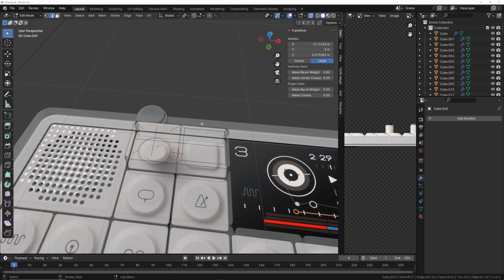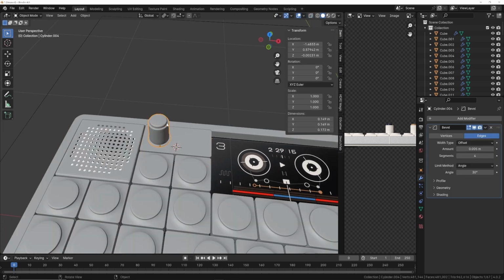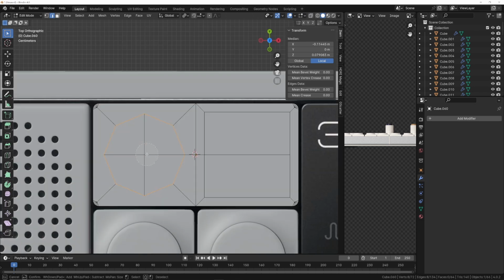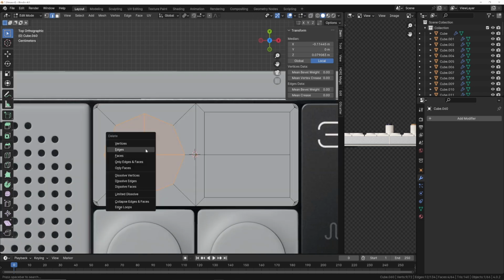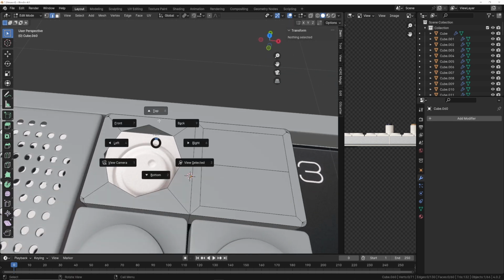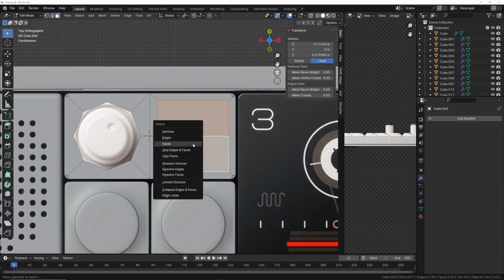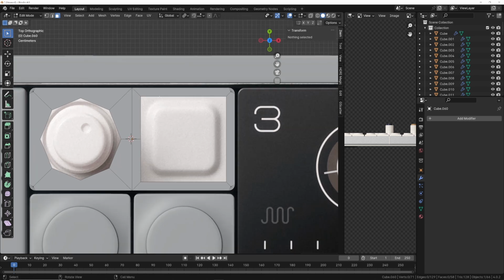And then basically what we need to do is I'm going to go add Alt-Z. I'm going to hide this for now. Tab. We're just going to go in here. We're going to grab these 3 faces and just delete the faces. It's going to give us the hole. And then similarly over here, let's just grab these 2 faces here. Click 3, delete the face. That's going to get rid of this line that we don't need in the middle.